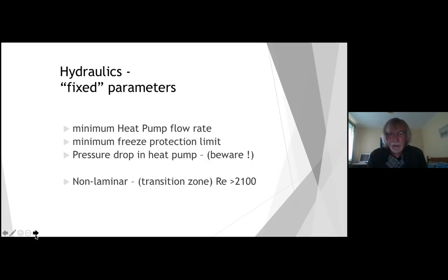There's a starting point. That is what the total flow rate around the system is going to be. The other thing that the heat pump manufacturer will very often specify is what minimum freeze protection they want on the heat pump. It's nominally usually minus 10 C. Some heat pump manufacturers want minus 15. So be alive to that, but that's another given for you.